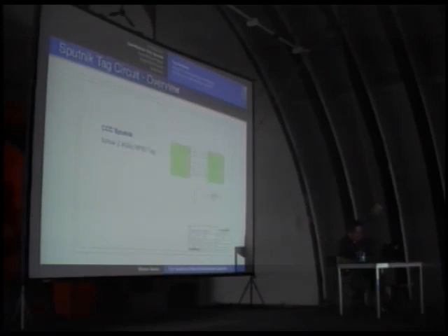No. If you have a line, then the line is automatically connected if it shares the same name. So this makes a sheet more reasonable. If you have a line here that's IRQ, it's automatically connected to another line that is also called IRQ, if it's on the same sheet. This ensures that you don't have wild crossings between all kinds of lines and you lose complete track. So first look at the names for the lines and then you see where they go.